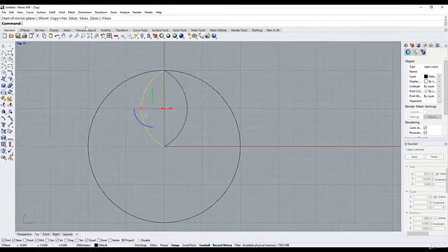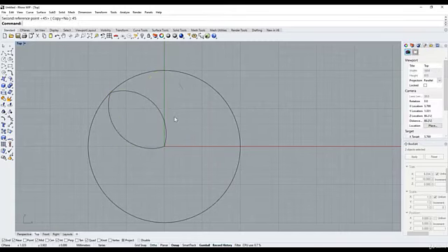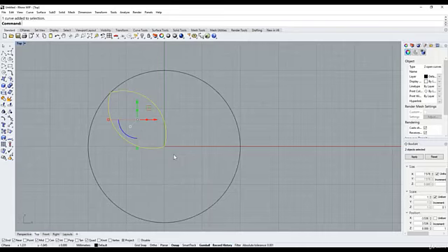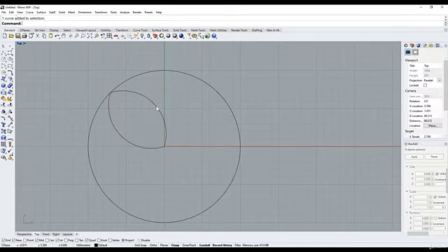And the y-axis, okay, that's nice. And I'm going to, what do I want to do? I want to rotate that. I'm going to type rotate, center of rotation being 0, bring that up and 45 degrees, lovely. And I want to select both of those and join those. So now we've got a closed curve.